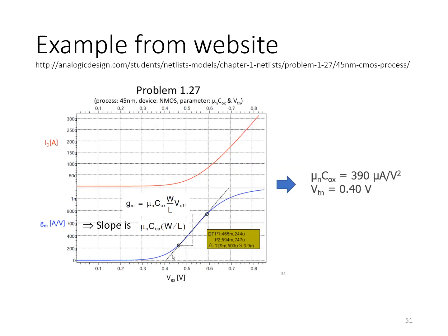And the resulting plots you see mirror very closely the cartoons that I was showing in the past. Here is an example of finding the threshold voltage, and using the slope of this part of the GM versus VGS curve, you can estimate the constant mu nCox.